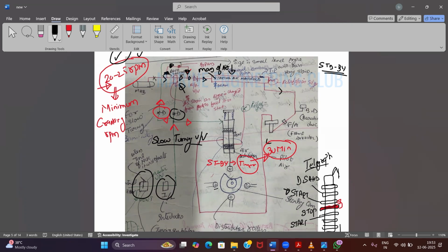And this 7 bar is obviously going, it will do the normal part. The same air is going to come over here, but the amount of air that I am going to inject will be very less as compared to your auto starting valve when it opens. So if the amount of air quantity is less, it will turn my engine slowly.